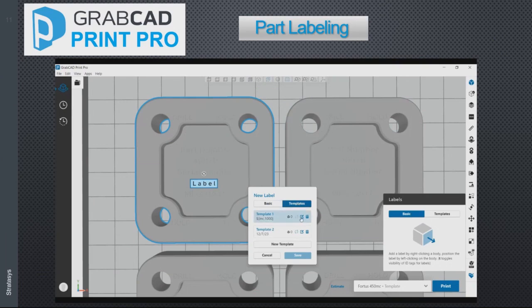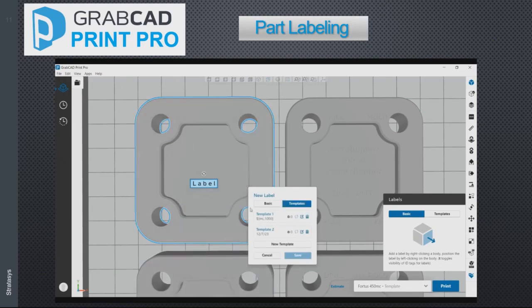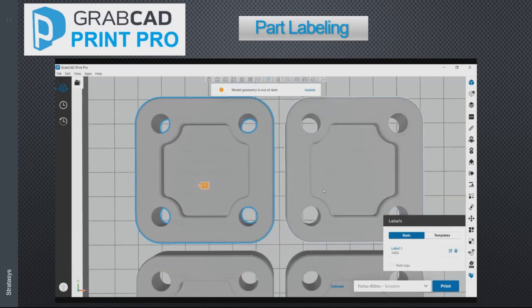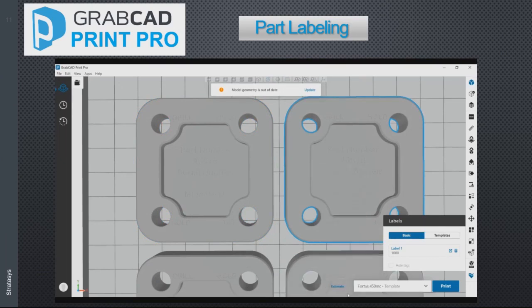So this first template I have here is a numbering template. So we're going to start at 1,000, and this will numerically increase each label by 1 number. So I'm going to apply that to the first part. Now I'm going to go to the second part, add label to body.